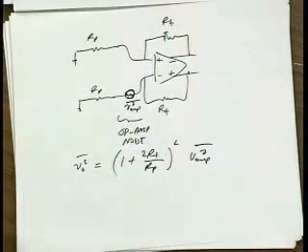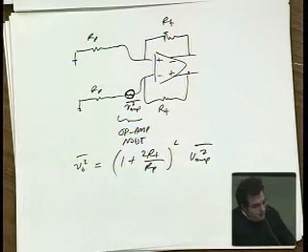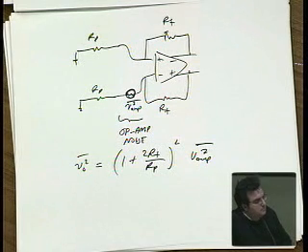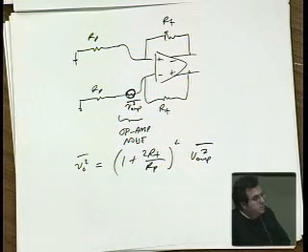Yes? Is this an impedance or real resistance? It doesn't matter. It's not a real resistance, but it acts effectively like a real resistance. Okay. Take 240. That's a quick answer. We study circuits like this in 240. But basically, since you're charging and discharging a cap through a switch, you're injecting thermal noise onto that capacitor.